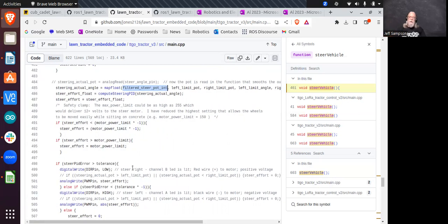As soon as you get your value from either your joystick or from ROS, at that point is where you want to limit how fast that can change on you. So you want this code to stay the same. You want it to follow the requested target position, but you just want to move your target position at a much slower rate than whatever's coming in from the outside world.